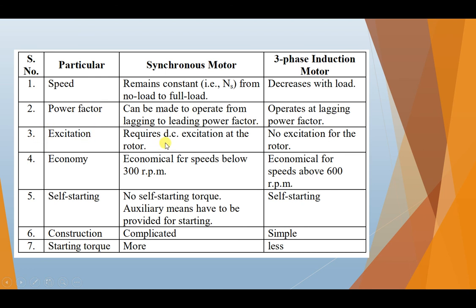Excitation is required in the synchronous motor and no excitation for the induction motor. Synchronous motors are economical for speeds below 300 rpm, and three-phase induction motors are economical for speeds above 600 rpm.